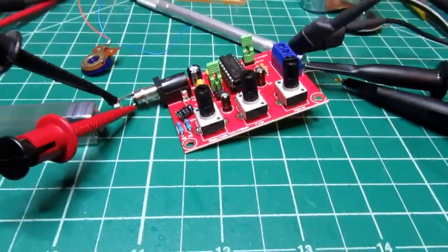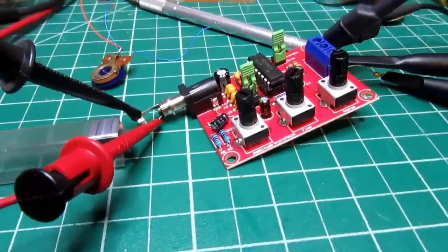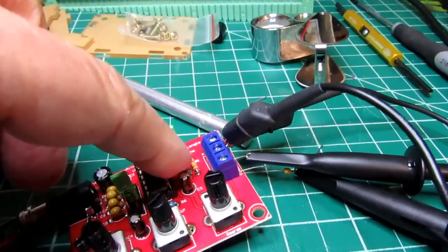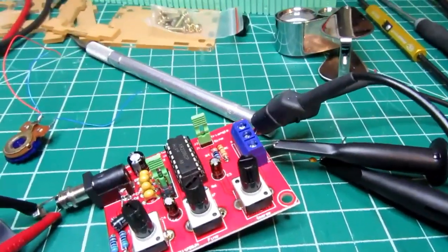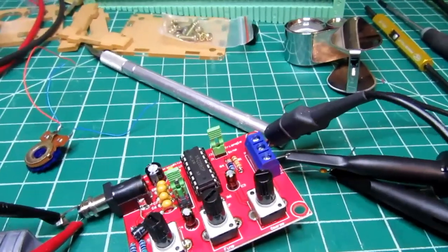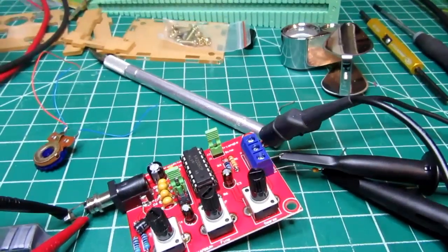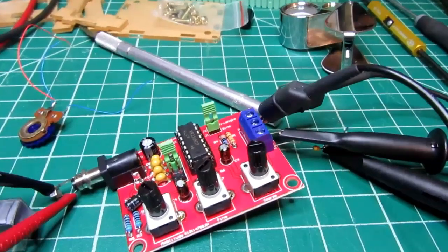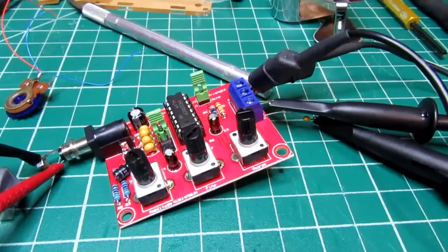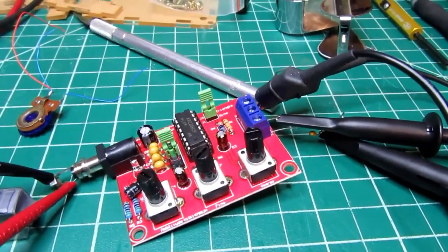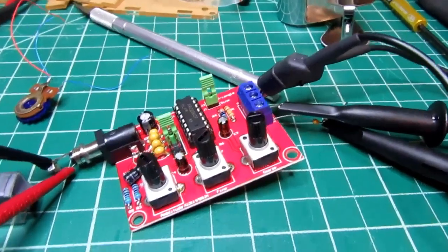Alright, I realized that I needed to fix this one resistor R1 over here. That was a 1K. It should be a 10K according to the data sheet, and it's really too low of a value considering that the square wave output voltage is going to be considerably higher than any normal logic level you're likely to use.